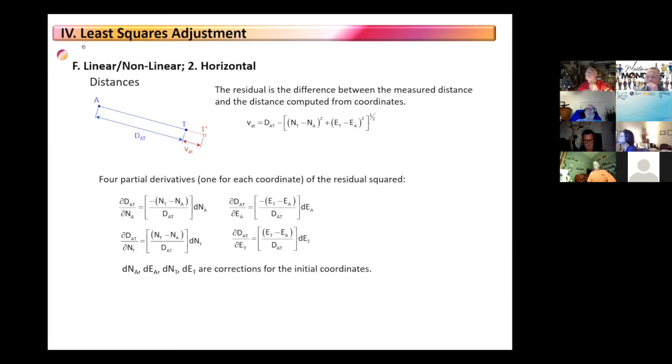That's why you'll see in most adjustment software, one of the things that it tells you when it's done computing or adjusting a network is it says it converged in 3 iterations. That's what it means, that it's come down to its tolerance level within 3 runs through the network. Okay. Now that's just for one distance, and that's just for distances.